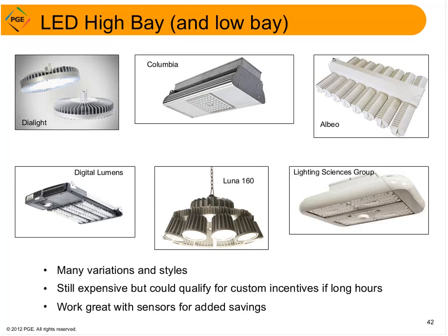As you can see from these pictures, LED high bays come in many shapes and sizes. And again, because fluorescent works well, it's going to take a while for LED high bays to be a mainstream alternative. The performance is good, but the fixtures are at least twice as expensive as fluorescent right now. So the applications that currently are cost effective are ones with long hours of operation, and especially cold environments like large frozen storage warehouses. LED fixtures work great in this cold environment because they like it cold and they don't mind frequent switching. And the LEDs will come to full brightness instantly.